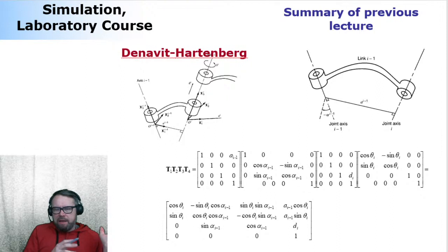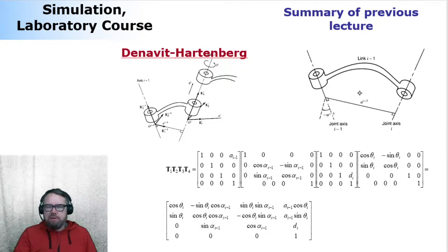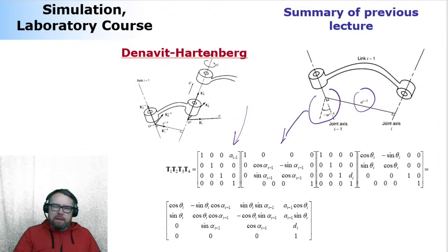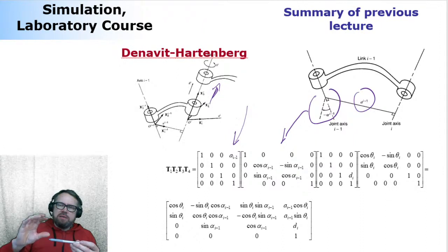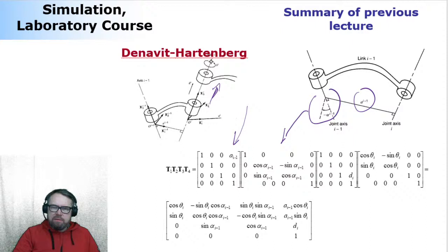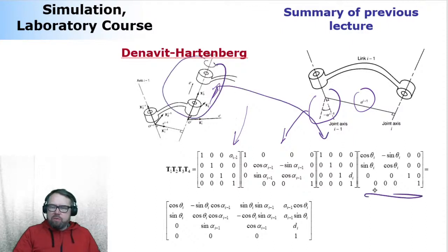And these parameters are the length of an arm, this one here; how much they're twisted, like if there's a twisting of the body, this one here; what is, let me see, d here, how much they're separated in a translational joint, like how much they're away from each other; and what is the relative rotation between the bodies, this one here.